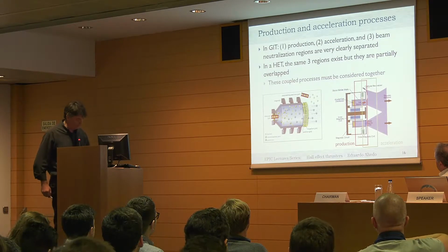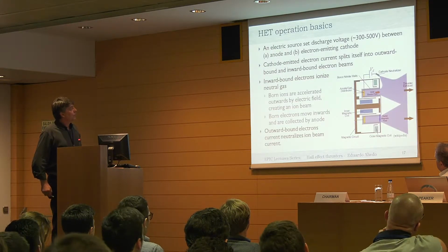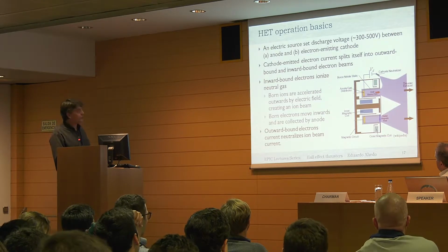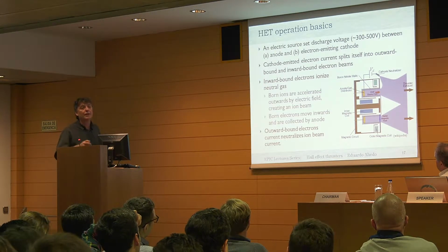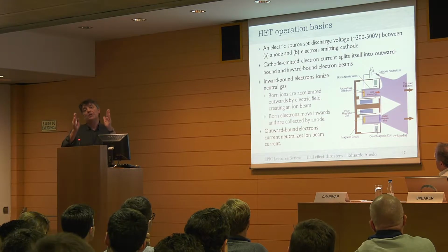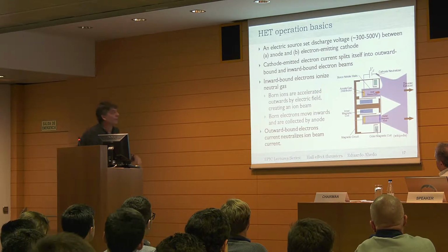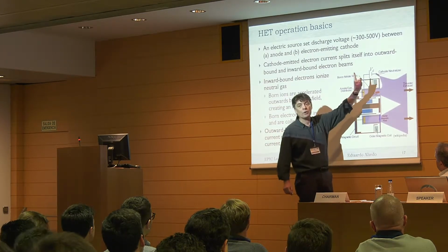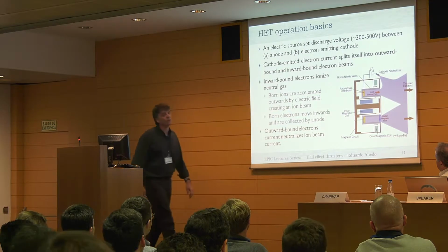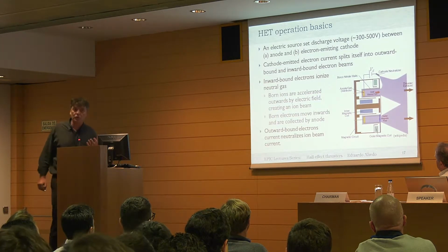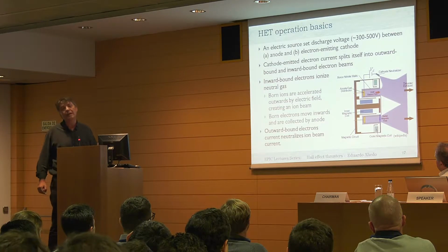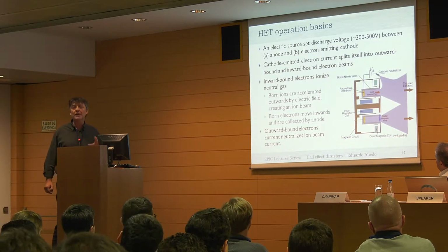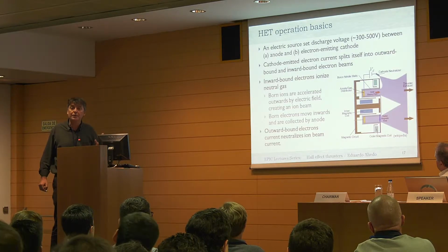These are the similarities and the differences with the ion thruster. Here we have a discharge voltage, and we don't have grids. The discharge voltage, or the potential we're going to get for acceleration of the ions, comes from the cell between the anode and the cathode. We have only one cathode, which is the neutralizer. We are using lower potentials, not 1,000 volts, typically around 300 volts. This makes the PPU simpler. Also, we have fewer electric points to control.